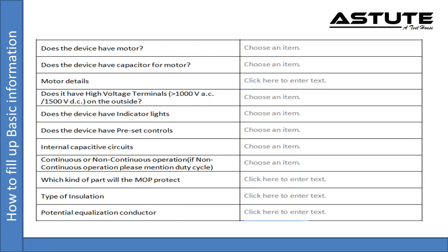The colors of indicator lights and their meanings shall comply as follows. Red, warning. Immediate response by the operator is required. Yellow, caution. Prompt response by the operator is required. Green, ready for use. Dot matrix and other alphanumeric displays are not considered to be indicator lights.